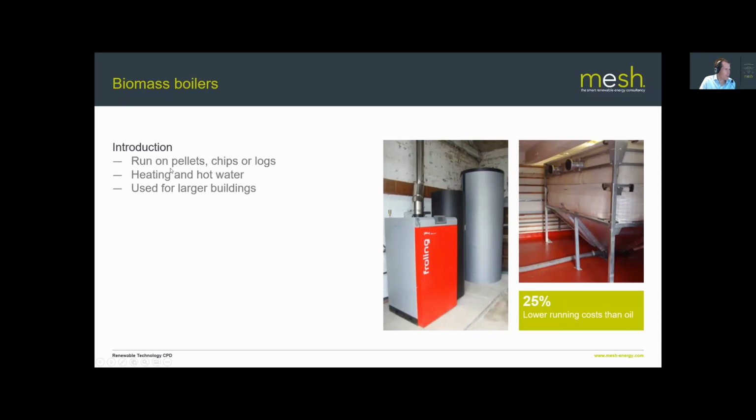They can run on pellets, chips or logs, and they're used for basically heating up the hot water. They'll give you the high flow temperatures that a heat pump will struggle to get, or if it will get there, then it will do it at a relatively high cost. As I say, often used for larger buildings.